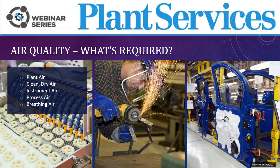When designing plant air systems, people have different expressions to indicate the overall level of air quality needed. We hear shop air, plant air, CDA, or clean dry air. We hear instrument air, and these are commonly understood, but they're not really well defined. Instrument air really is a classic example, and many think it requires a desiccant dryer, but it's not necessarily the case. It really depends on ambient conditions.